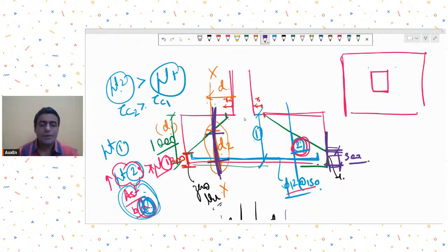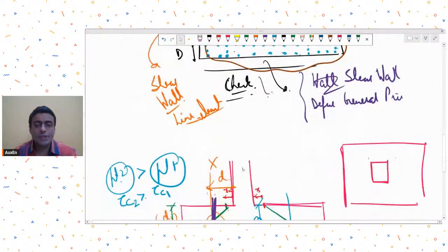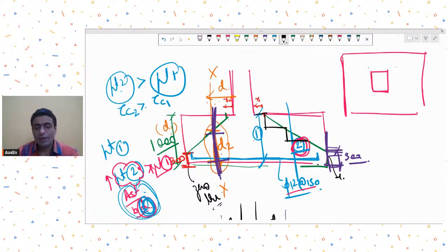Okay, good. So this was about the sloped footings, trapezoidal footing, sorry. And in the same manner, you can give the step footing also. So the same logic you can adopt for giving step footing. Wherever or however you decide the profile of the step, ensure that at every step you check the one-way shear and also check the punching and accordingly decide the step profile.